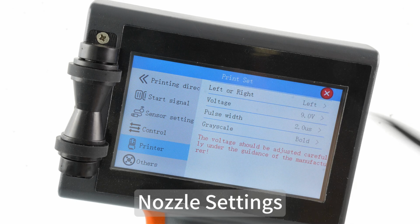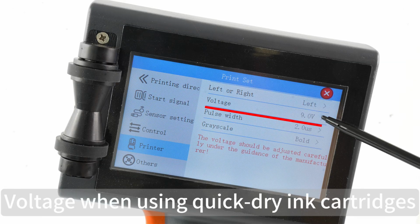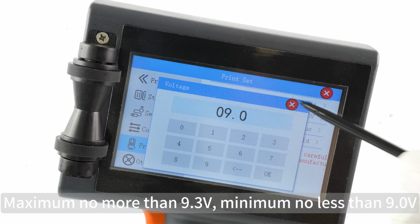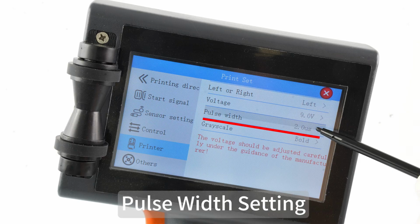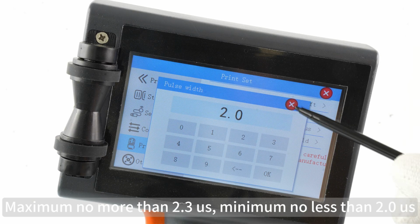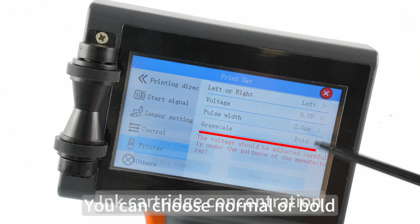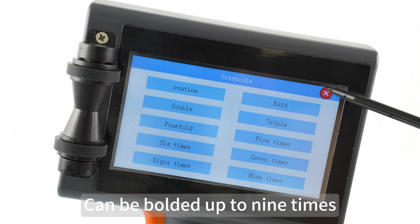Nozzle settings: nozzles can be switched left and right. Voltage when using quick dry ink cartridges: maximum no more than 9.3 volts, minimum no less than 9.0 volts. Pulse width setting: maximum no more than 2.3 us, minimum no less than 2.0 us. Ink cartridge concentration: you can choose normal or bold. Can be bolded up to 9 times.